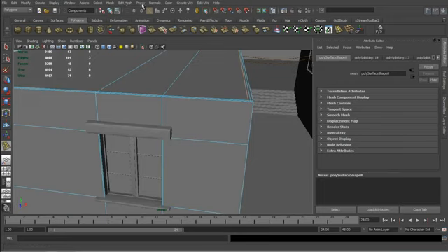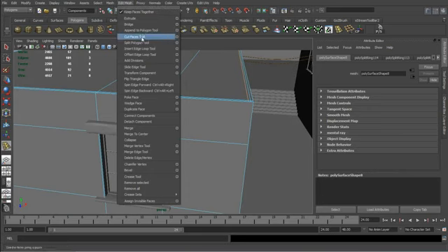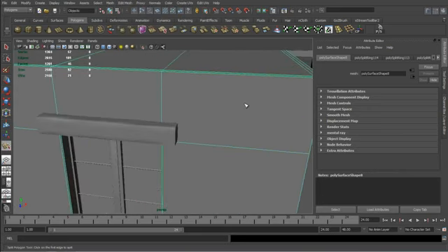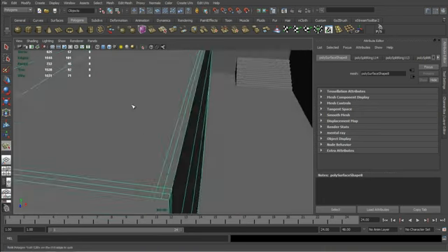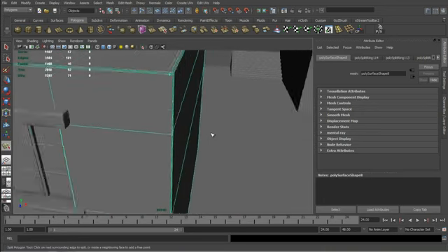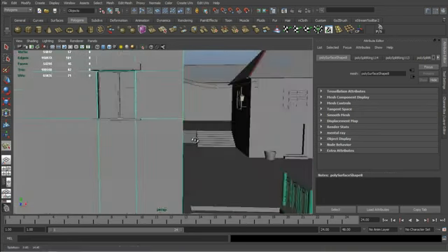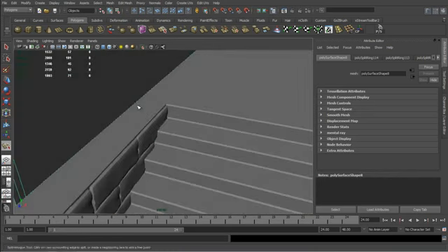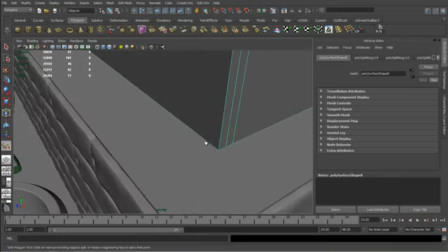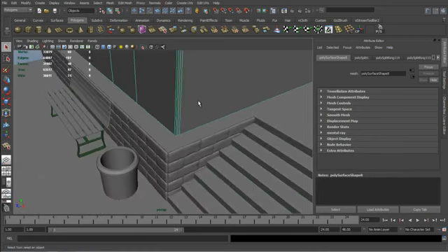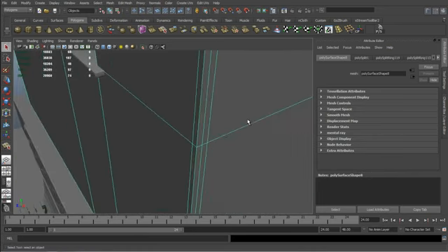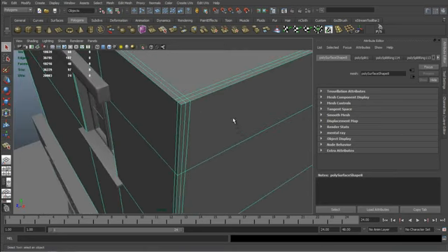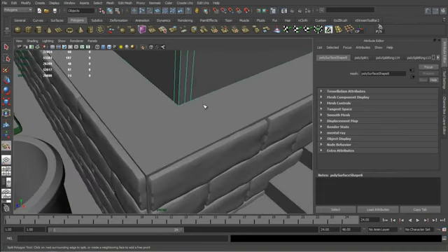So to fix that, we're going to the edit mesh, select the split polygon tool, and that way we can manually finish the rest of the loop. Just selecting the starting point and then the end point and hitting enter, and doing the same thing again to create the 4th loop, or the second one on this corner.